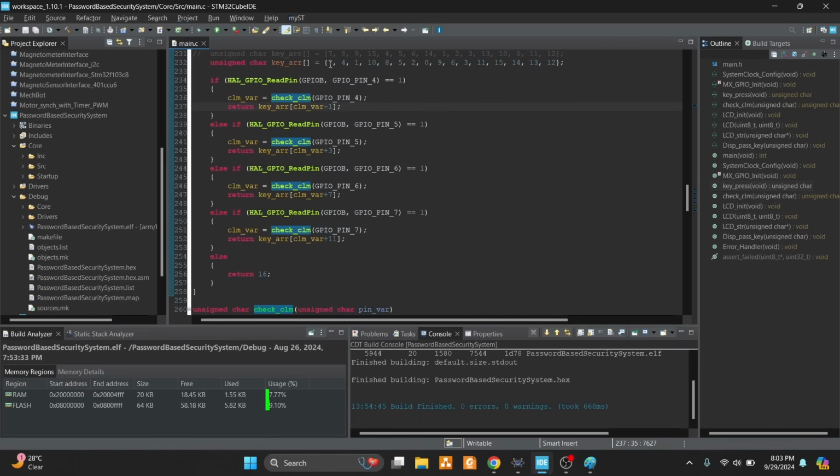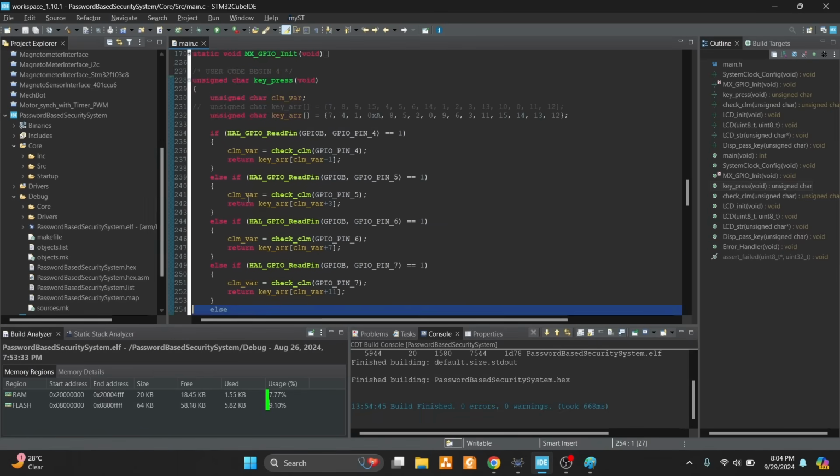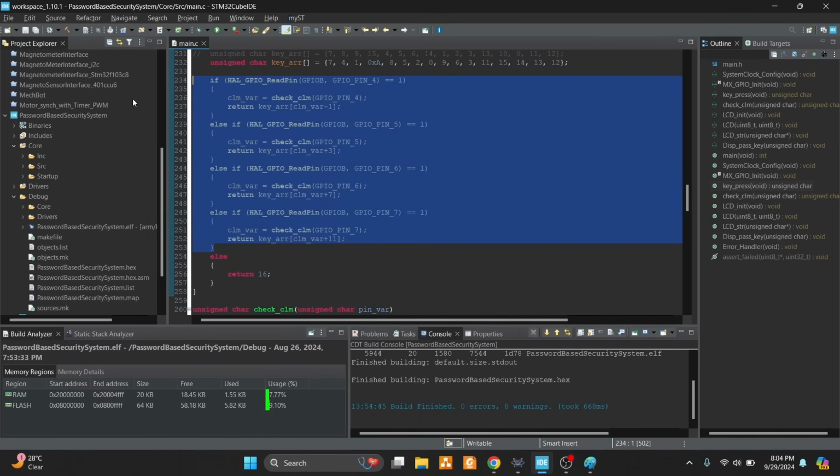In the first column, which keys are there? 7, 4, 1 and 10. I have assigned it as 10. Likewise for A, B, C, D, I have assigned 10 because A in hexadecimal means 10 in decimal. So we can also write it as 0xA, which will be more understandable. If none of the keys has been pressed, by default it will return a value of 16.